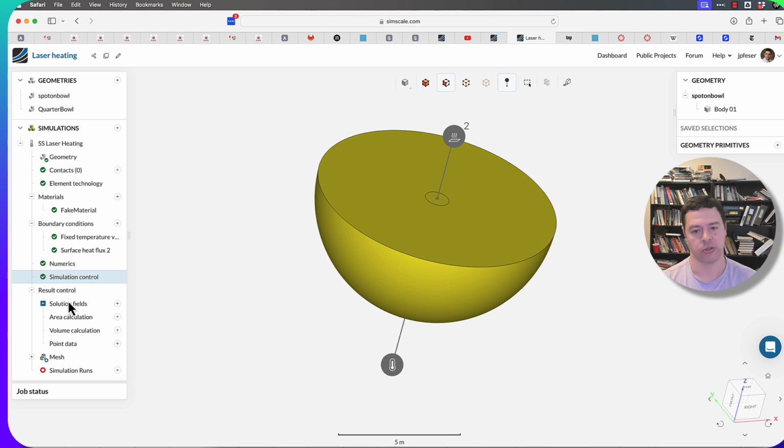When you get the solution to whatever is happening here, what it's going to spit out when you're done is the entire temperature field. That makes for a pretty picture, but it doesn't make for a lot of really good engineering numbers most of the time. Typically what you want to know is one scalar value or some global value, like an average temperature rise, or you just want to check to make sure that energy was close to being conserved.